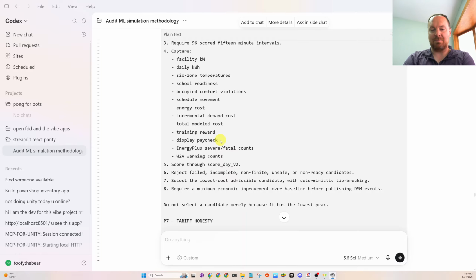The RL agent or grid search will gamble on when they want the HVAC system to start. They do the gambling once at midnight, and then we have a schedule for the building. Then we'll use that schedule to manipulate BACnet points to turn true or false, on or off, based on the current computer time.